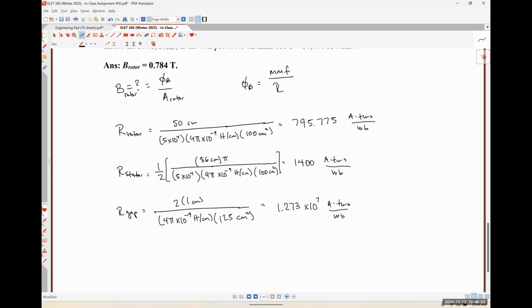It's a pretty interesting scheme where, I hesitate to call it magnetic attraction, but effectively the properties of reluctance are such that it's always trying to minimize it. So it's dragging the rotor around to try to make the area of the air gap larger at all points and times. And you just tune that to energize coils in a specific pattern, and it's constantly pulling the rotor around in order to minimize the reluctance. So it's a reluctance-based machine. Pretty neat. Yes, I've heard about that.